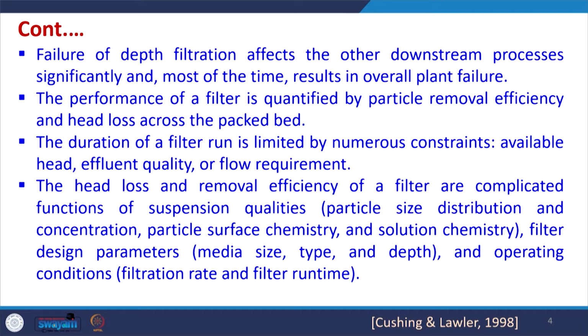So, both are very important parameters. The duration of a filter run is limited by numerous constraints. How much time a filter will operate will be dependent upon the available head, and the effluent quality going through the filter. So, whether our sedimentation unit is working very well or not. If the sedimentation unit, or the units before the filtration units, are working very well, then the filter may also work very well, and so overall effluent quality after the filtration will be good.